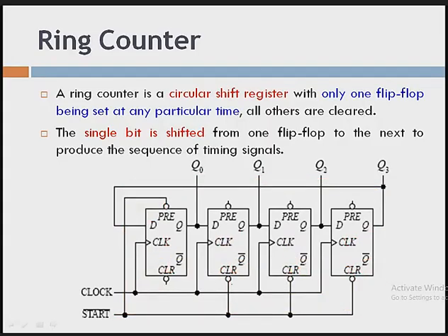Okay, you do not need to connect its clear pin. Only the preset pin needs to be connected, just like this setting. Only this setting you have to do. You can set any intermediate flip flop, no problem, but for understanding I am considering this flip flop initially. We are considering this condition, and how the data is shifted as we apply the clock pulses, we'll see in the next slides.